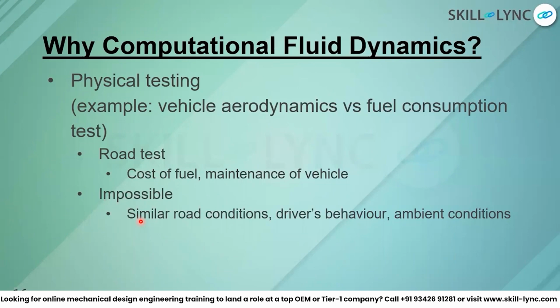Now, the road conditions, driver's behavior, ambient conditions. The weather today, it's windy. Today the air is moving opposite to the vehicle, so your fuel consumption will be high. The next day the vehicle is moving in the direction of the wind, on a very windy day, so you might have an advantage in fuel consumption. And if there is a crosswind, that can also affect the vehicle handling.